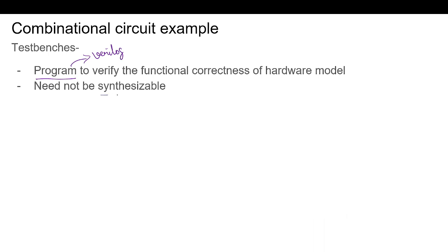And these test benches are not usually synthesizable. Keywords like initial are not synthesizable. Synthesizable means we will not be able to convert them to hardware.